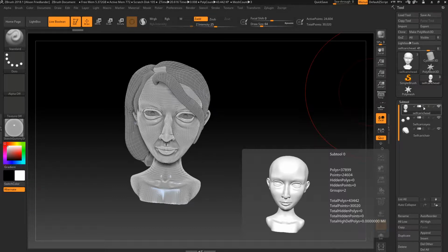So what you want to do is, hopefully you guys can see it, there's a bunch of different overlapping circles denoting the different types of Booleans that you can do. The first one is a Boolean union. The second one, with the crescent circle and a mini cutout, is a difference. And the last one is a Boolean intersection. So depending on the operation that you want done, select the different Booleans.